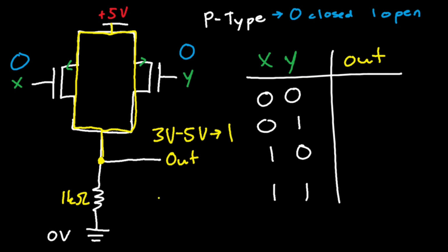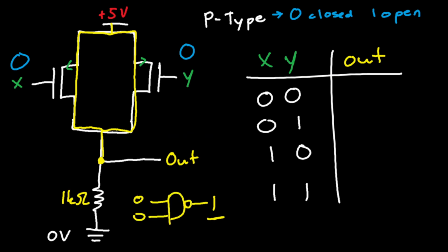of 1. So in the case of a NAND gate, let's say there was input 0, 0. When you input 0, 0 into a NAND gate, you get 1. So in this case, since this 5 volts was able to flow down and reach this output node, that means you have 5 volts at this node, correct? Since you have 5 volts at this node, that means the output is logic 1. And since the output is a logic 1 here, the output of this NAND gate would be 1 when you have 0, 0. Or this hypothetical gate. Nope, I'm not saying NAND gate yet. This hypothetical gate would have an output of 1. Let's do undo instead.